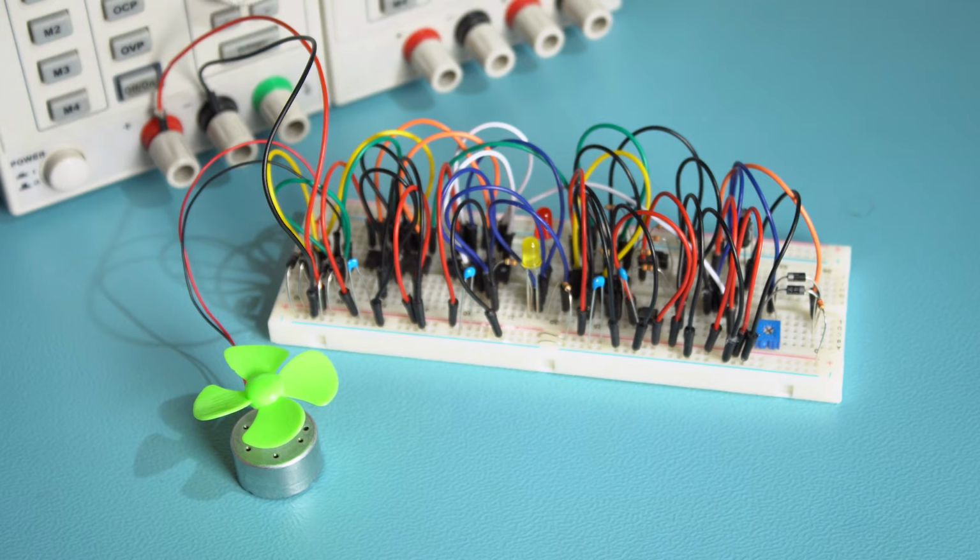When you turn on S1 and S4, the receiver will be connected between higher and lower potential, which will force the current flow. When we turn on S2 and S3, the current will also flow through the receiver. There will also be voltage but directed in the opposite direction. Let us now swap our keys for transistors.